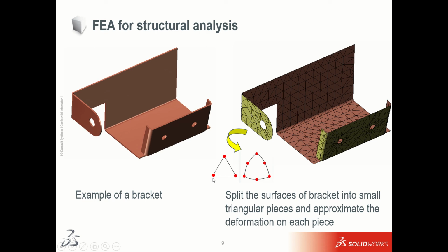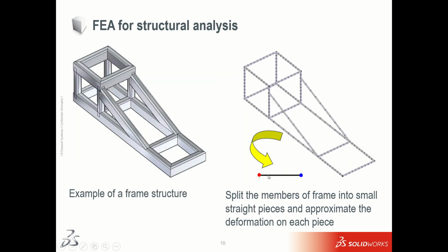Basically, 3 translation and 3 rotation. And this basically comes for a thin or a thick element, maybe like a sheet metal part. You directly choose this shell element, and the time required to run the analysis for a shell element is less than for a solid element.